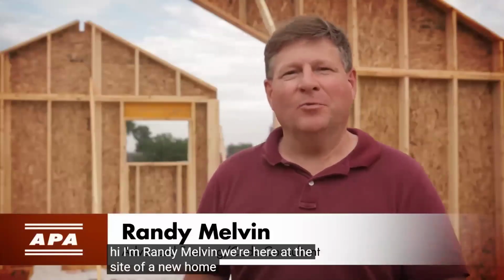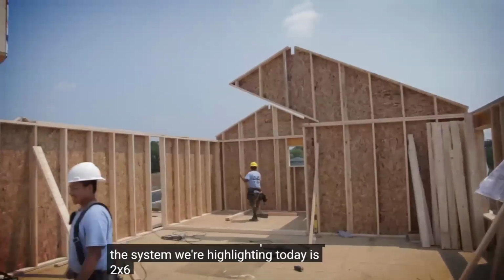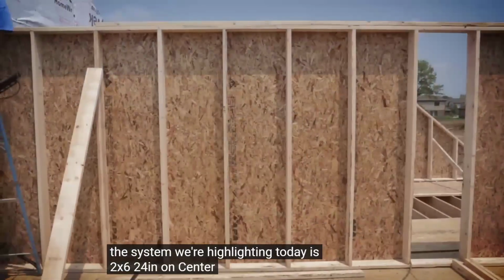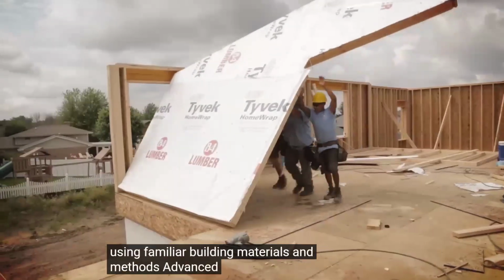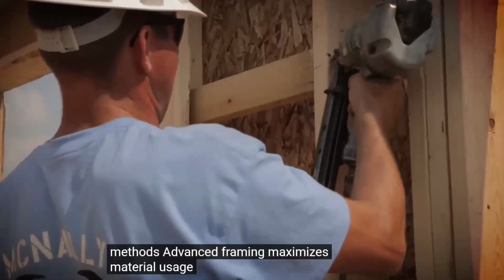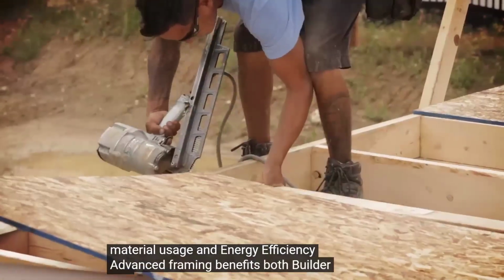Hi, I'm Randy Melvin. We're here at the site of a new home in Lockport, Illinois. The system we're highlighting today is 2x6 24-inch on-center advanced framing. Using familiar building materials and methods, advanced framing maximizes material usage and energy efficiency. Advanced framing benefits both builder and homeowner.